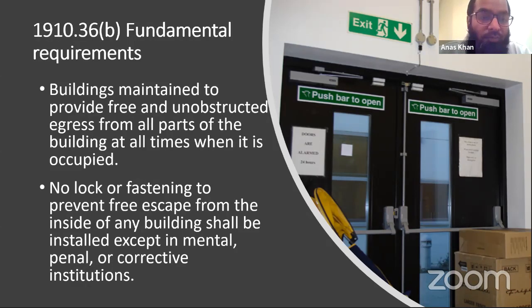Right? So in these areas you can lock the emergency exit, but as required by the OSHA standard, the key shall always be available to the duty officer who is there, right? And other than these areas, emergency exits shall not be locked. There are some other requirements of emergency exits which we are going to discuss in the next slides. Yes, any question?